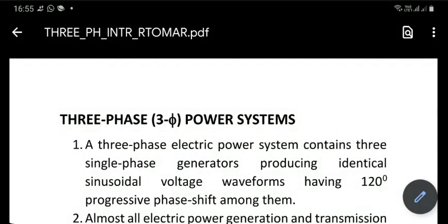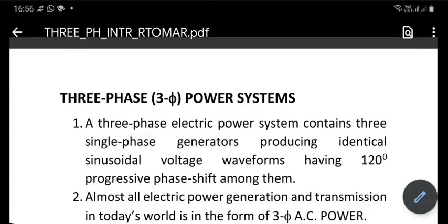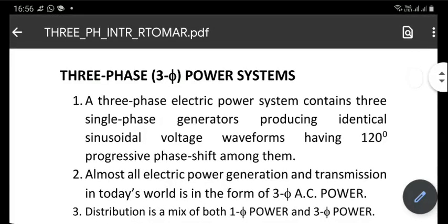Invariably, the entire world uses three-phase systems to supply bulk power to customers. There were times when people experimented with two-phase systems also. Have two generators connected with some phase shift between them, etc. But it turned out that although theory allowed that possibility, in practice, the amount of effort involved with two-phase systems was not that different from the amount of effort you would need to build three-phase systems. And three-phase systems still have much higher power carrying capacity for the same transmission line.